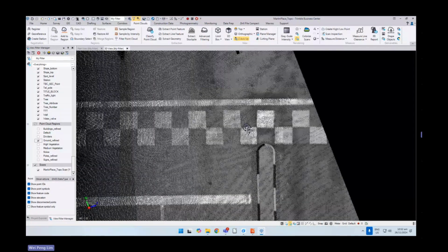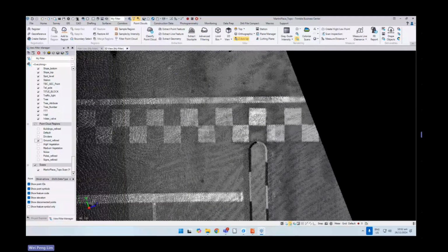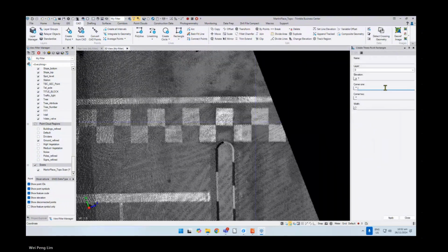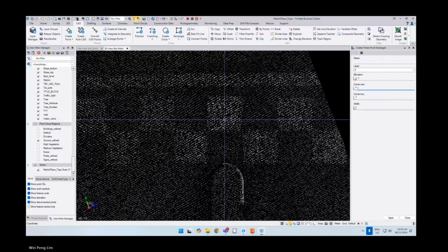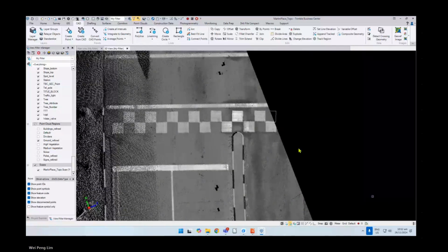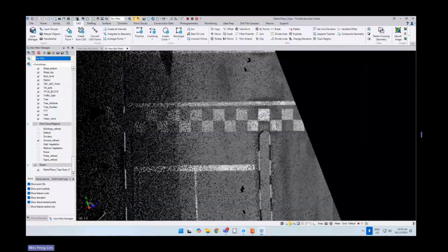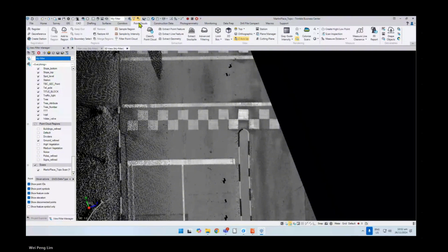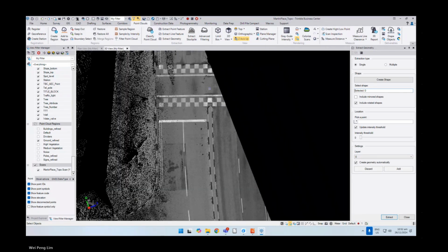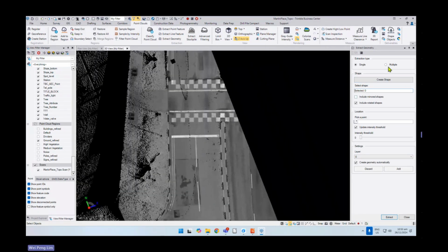So first of all, I will draw something. Let me go to the tab function here. Rectangle, I draw a 3-point rectangle. Let's say I draw this rectangle, where this is over here, and then I can use the extract geometry function here. So I can extract multiple.